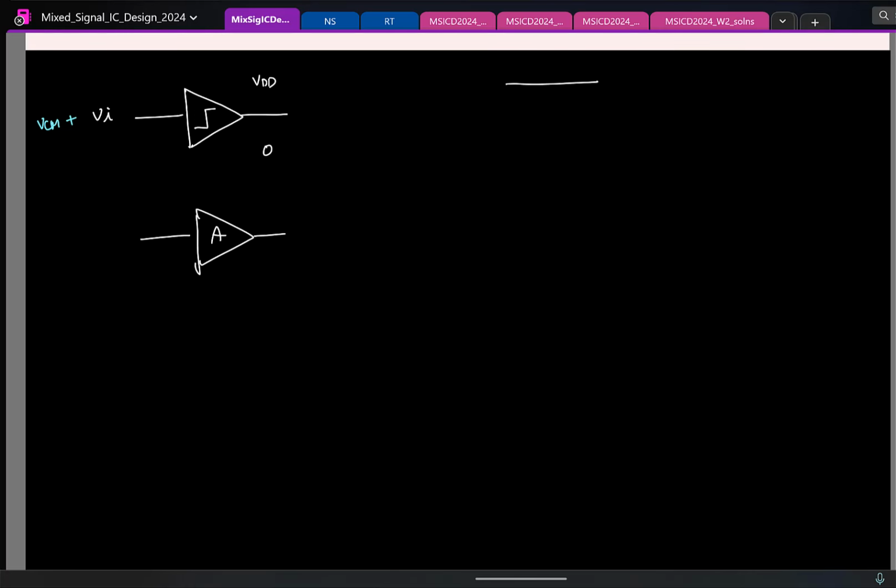Put a resistor here and then have a common source amplifier like this. Simplest circuit. And what is the gain of this? Magnitude of the gain? Gm times R. Fine. This much everyone knows, I hope. So this is good, but in practice we do a modification.